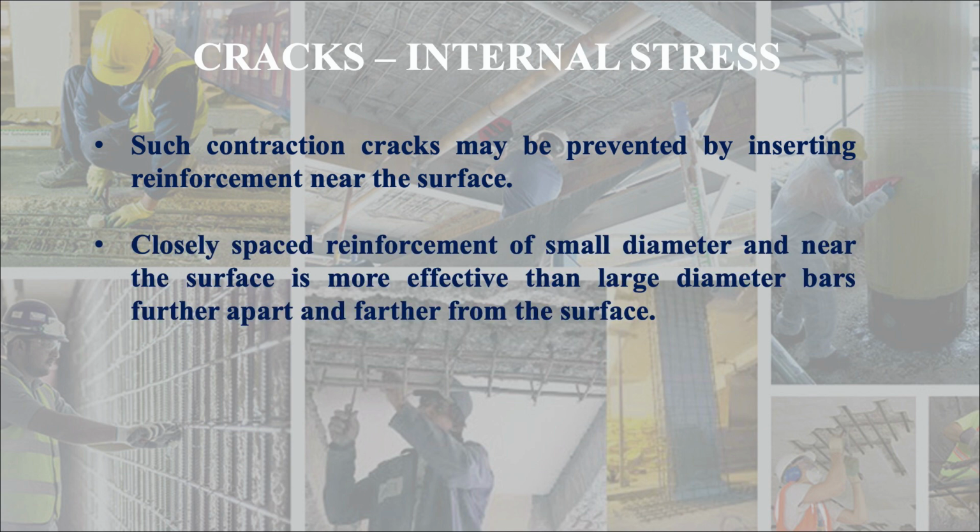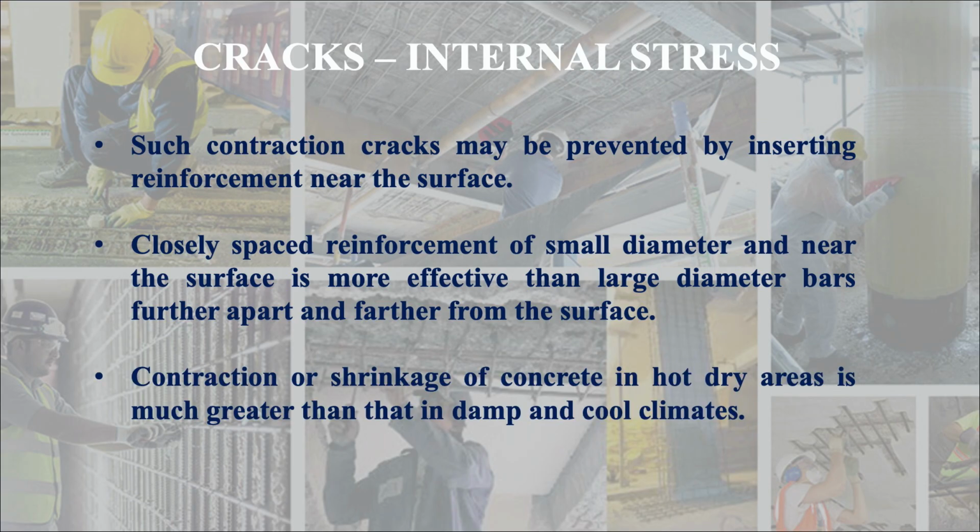Closely spaced reinforcement of a small diameter and near the surface is more effective than large diameter bars farther apart and farther from the surface. Contraction or shrinkage of concrete in hot dry areas is much greater than that in damp and cool climates.